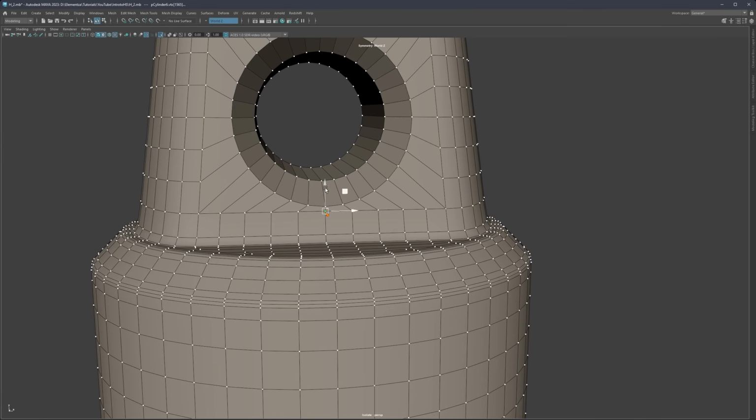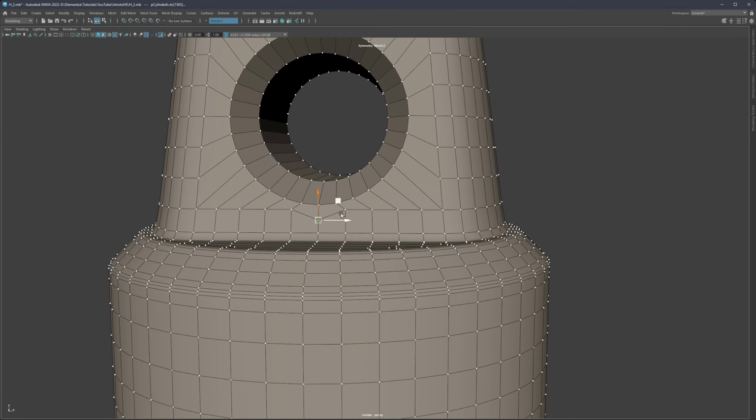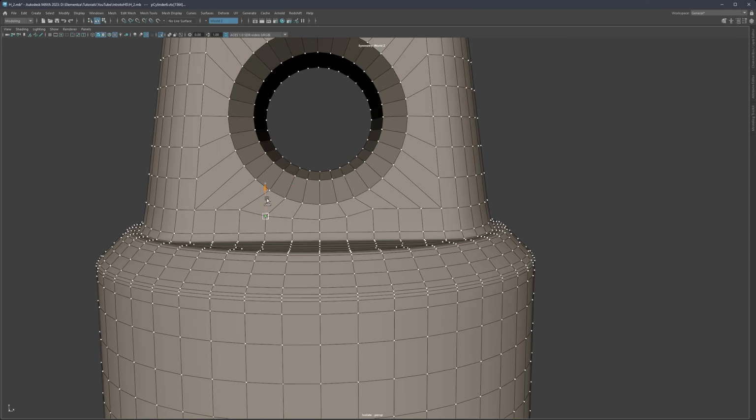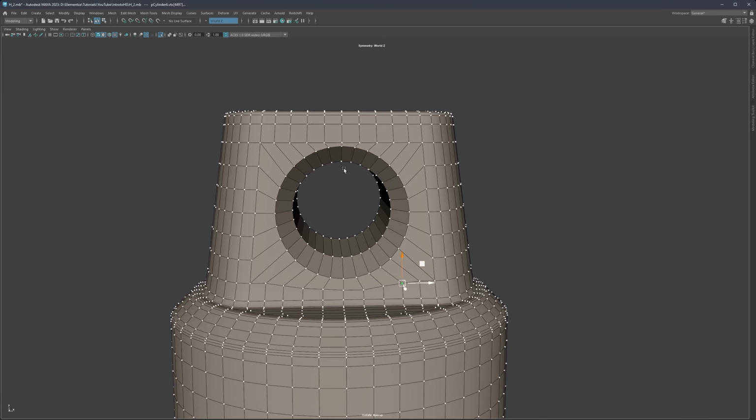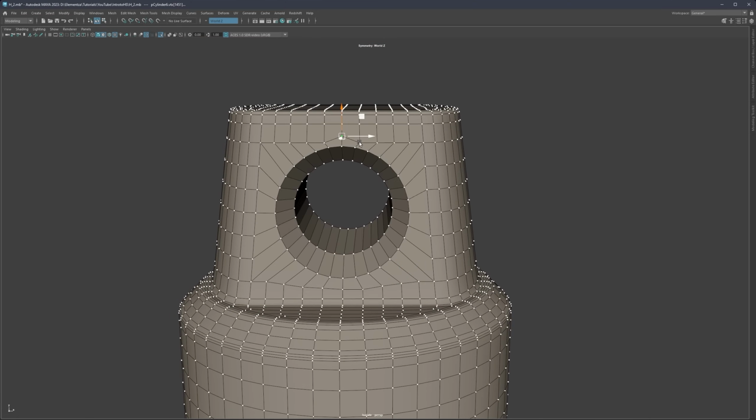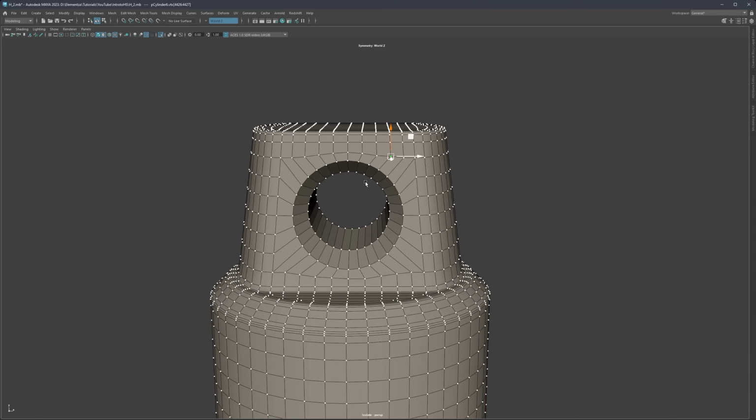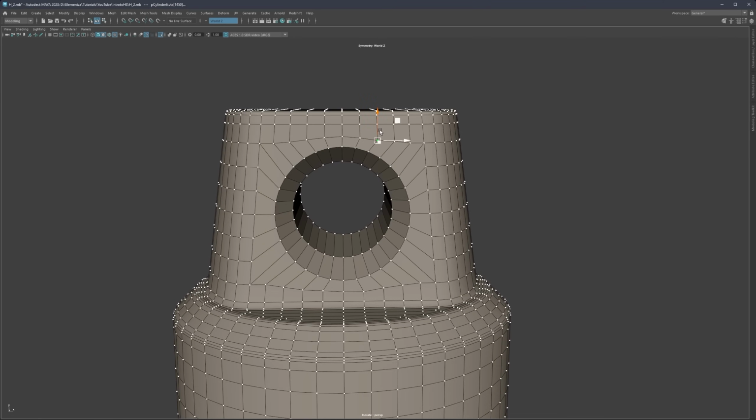So I like to do also, especially when circles are in question, just to adjust these points a bit more, like this to the side. So again, selecting a point and then shift control to slide. So we can just organize this a bit better to have more of a proper curvature there. So let's say something like this will be enough. So you can really now spend a lot of time organizing a bit more.